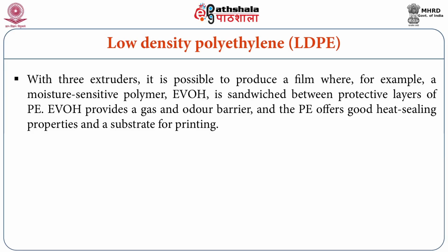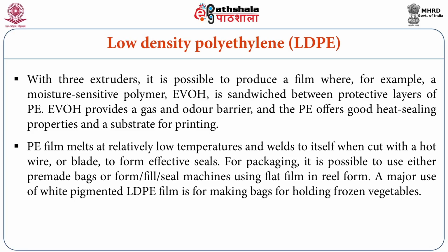Ethyl vinyl alcohol provides a gas and odor barrier and polyethylene offers good heat sealing properties and a substrate for printing. Polyethylene films melt at relatively low temperature and weld to themselves when cut with a hot wire or blade to form effective seals.